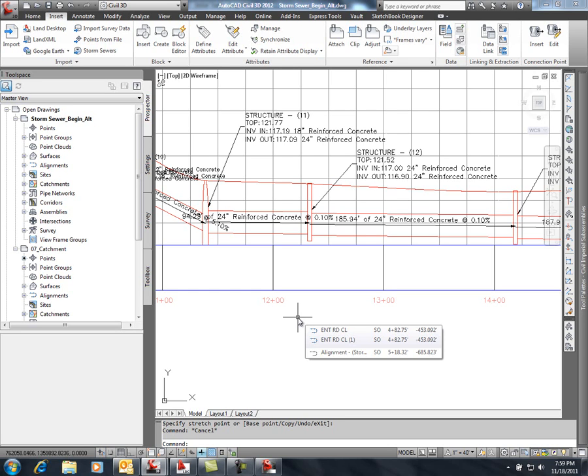We could also run it within Civil 3D such that if we were to migrate data over from Land Desktop, maybe as the basis to begin our design, we could start to add things like our catchment areas and flow lines to determine time of concentration, pass that directly from our model to that environment, make changes to establish our design, and then migrate that directly back into Civil 3D, which thus updates our system, all of our graphics, as well as our annotation.